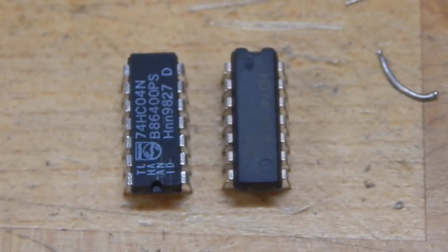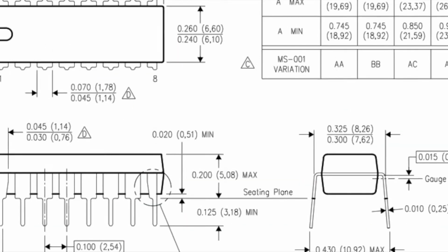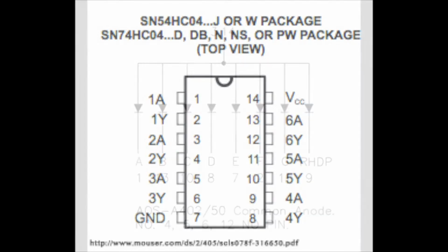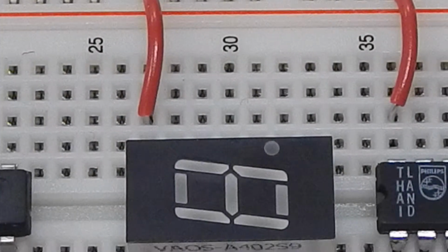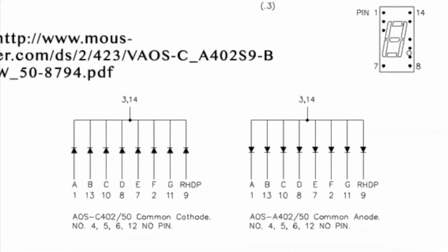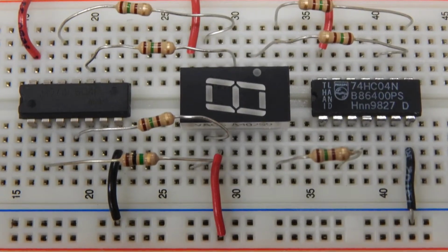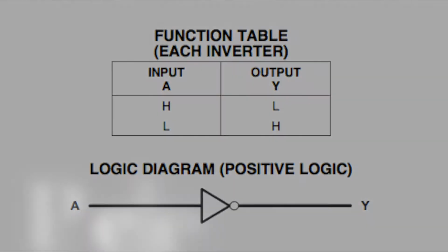For subsystem 3, we will use 2 NOT gates to act as a grounding component for the 7-segment display. The reason we are using 2 NOT gates is because each NOT gate only has 6 outputs, and we have 7 inputs that we have to put in. Since the 7-segment display has no ground and the diodes only have output, that is the reason we are using the NOT gates. So in theory, if we connect the output of the NOT gate to each diode, then the NOT gate will act as a current sink.